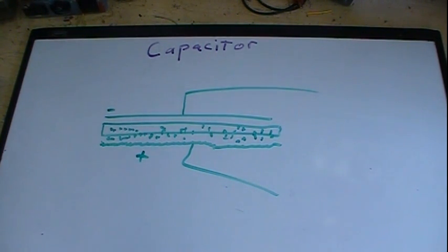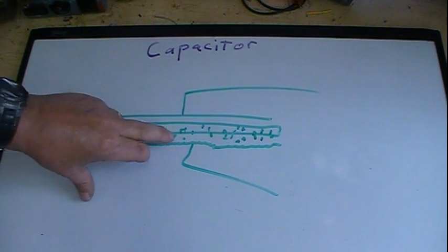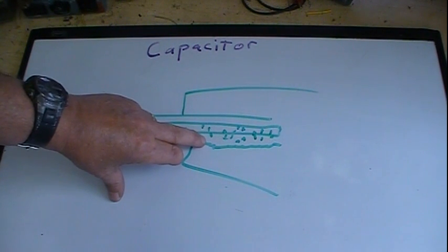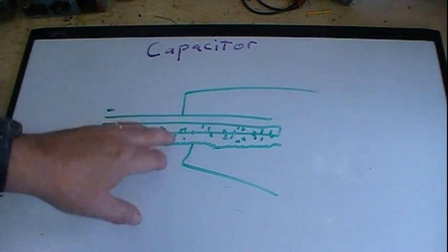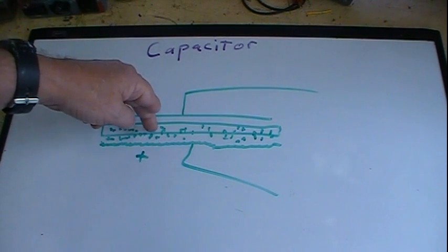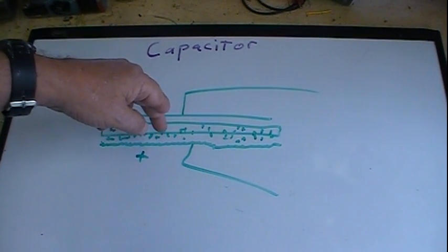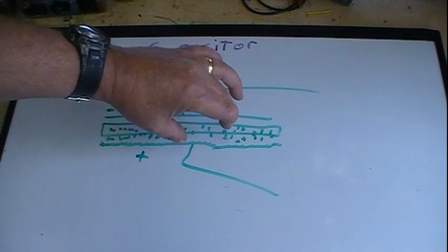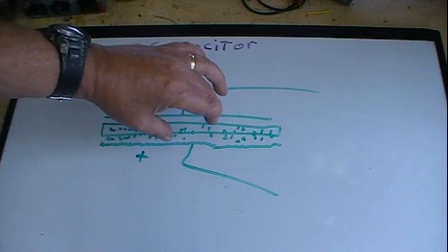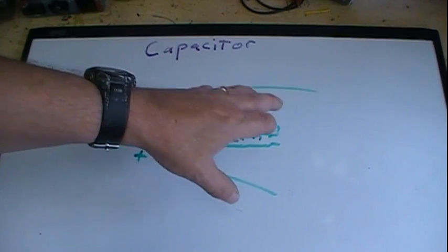And what it does is, as it operates, hydrogen bubbles will get on this plate, and that is your charge carriers, and basically is what creates a barrier and makes this plate positive. The electrolyte itself is the actual negative plate of the capacitor. So if this stuff starts drying out, you're losing your negative plate. So that's what happens with electrolytics. They'll start to dry out.